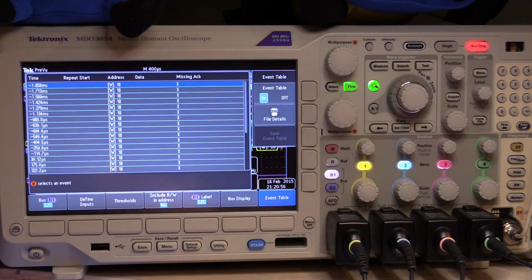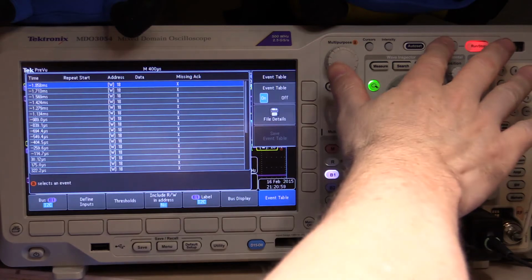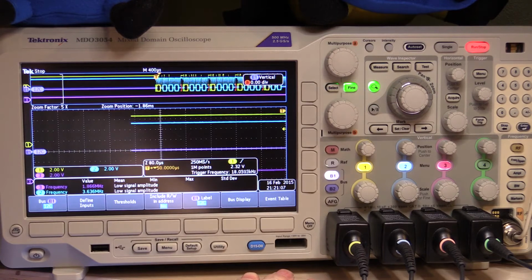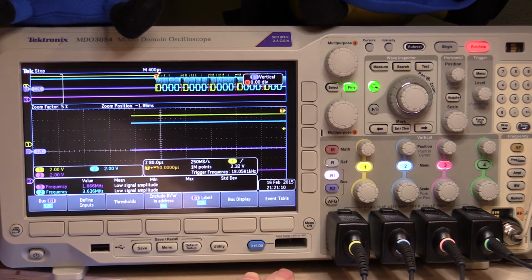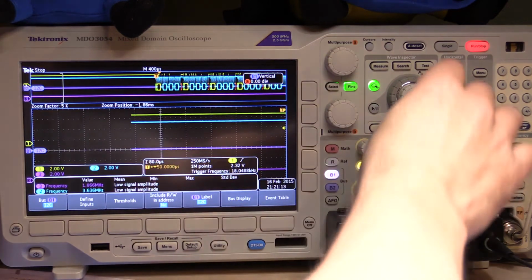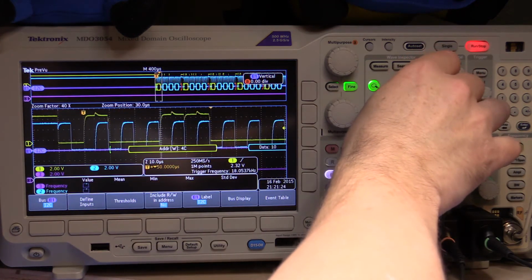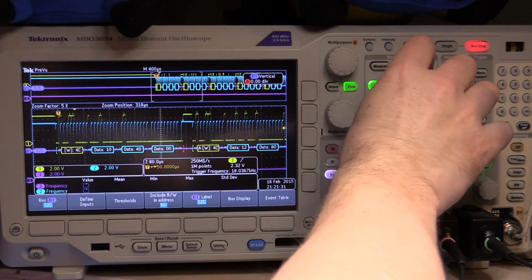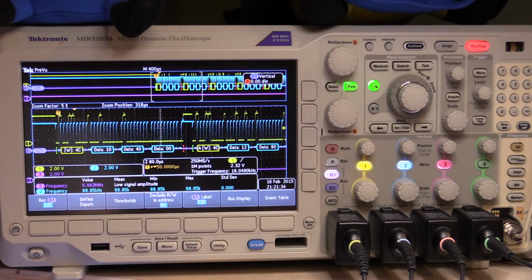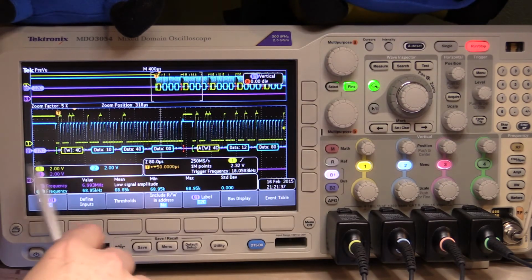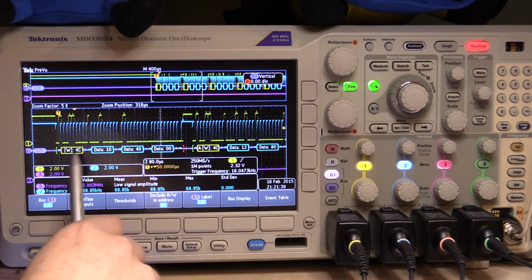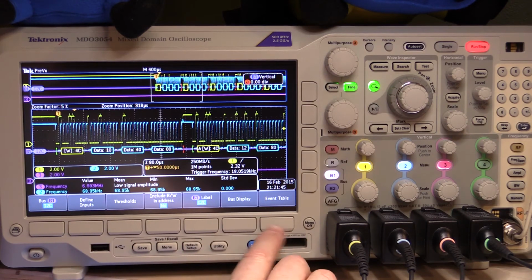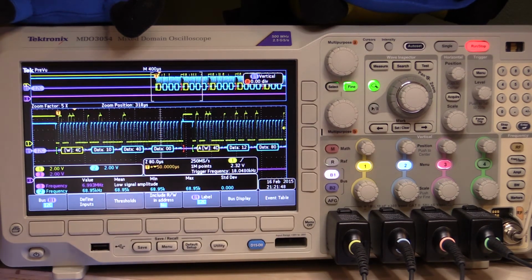I'm going to hit the reset on the Arduino and resample on the Tektronix oscilloscope, and we'll see what we get this time. So I'll let that go. Okay, well, I need to zoom in there, but that certainly looks a lot healthier. And oh, okay, there you go. So it's showing me 4Cs now, let me just widen that out a little bit, bring it into view. So now we've got 4C, which is the 98 less a bit. So the oscilloscope is actually taking the address bit off as well for its display. So obviously that aligns with that.